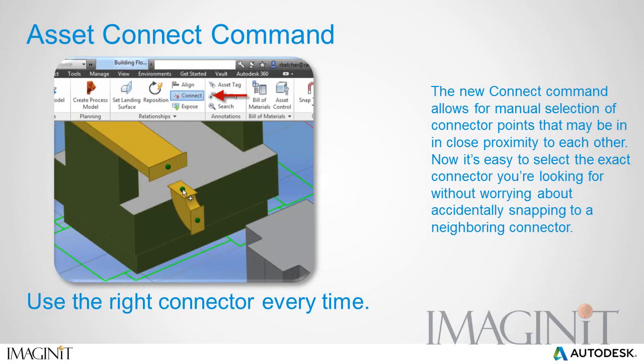The next enhancement we're going to focus on is the new Asset Connect command. If you've ever generated an asset with many connectors, you know how frustrating it can be when you go to place that asset and it actually inadvertently snaps to a connector you didn't intend to. The new connect command allows for manual selection of connector points that may be in close proximity to each other. Now it's easy to select the exact connector you're looking for without worrying about accidentally snapping to a neighboring connector.